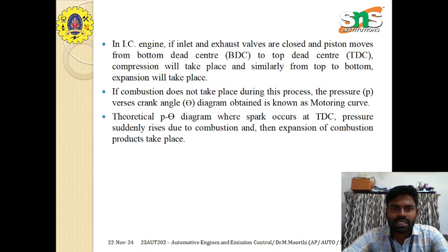So in an IC engine, if the inlet and exhaust valves are closed and the piston moves from bottom dead center, that is BDC, to top dead center, the compression will take place, and similarly from top to bottom, expansion will take place. So generally we have four strokes. If you take a four stroke SI engine, we have the intake stroke, compression stroke, expansion or power stroke, and finally the exhaust stroke.